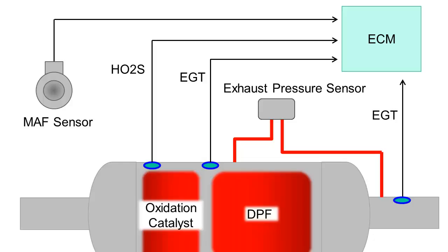For vehicles that spend a lot of time at lower speeds and loads, exhaust gas temperature is too low for passive regen, and soot will accumulate in that filter. When a specific soot load is reached, the particles are burned off at an exhaust gas temperature of 550 to 650 degrees Celsius. Soot load in the diesel particulate filter is calculated by the engine control module.